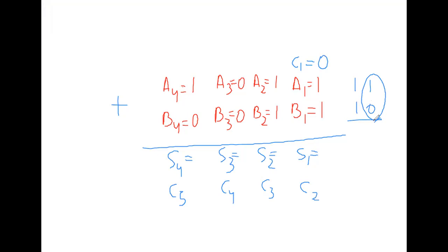That's why we have to assume that the carry bit is 0, because in a full adder we have three inputs, two inputs for these bits, but the third input should be the carry bit. So though in the LSB we don't have any carry, the carry value should be taken as 0, right?